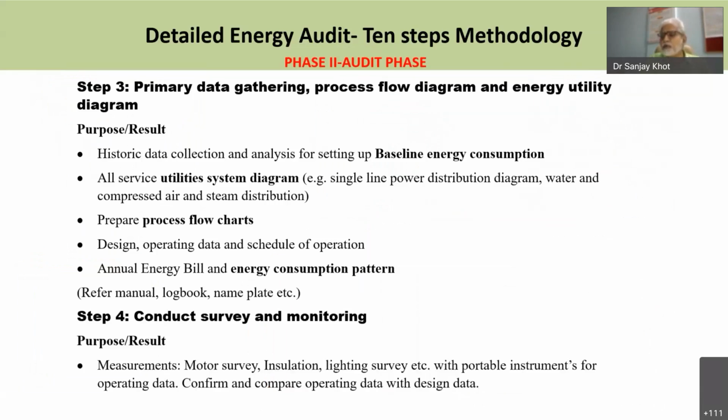Because if you go to a pharmaceutical industry, and a number of motors are there, suppose 10 or 20 motors of the same batch, then it is not necessary to conduct the audit for all the motors. Instead of that, you can identify sample motors, and there you can measure how much your motor consumes, and it has to be done like that.